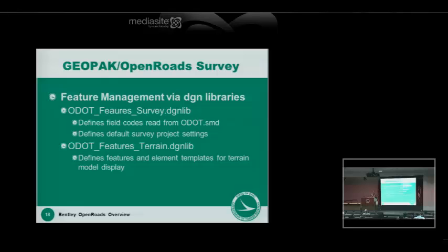So ODOT's code list is on the website, and if you're lucky, when you scope a survey consultant, sub-consultant, you get data using ODOT's codes, if you're lucky. Usually you get whatever codes they used, and then you've got to sort through it and do a find and replace if they send you like an ASCII reduced coordinate file or something.